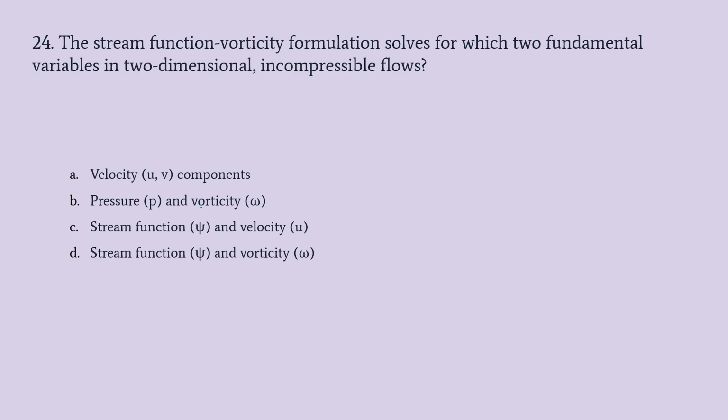The next question is about the vorticity stream function method for the pressure equation solution, or to solve pressures. So the stream function vorticity formulation solves which of the two fundamental variables in two-dimensional incompressible flows? So the question is, what does the stream function vorticity formulation solve? The stream function vorticity method is another method used to solve for pressure in incompressible flows.